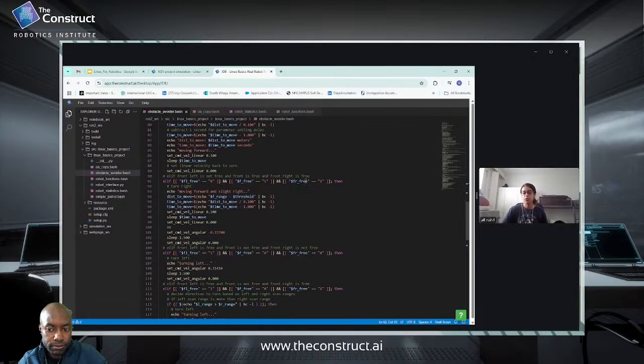So we're just doing a bunch of if statements here. So for example, here I have the front is free and the front right is free. And so this is the compound movement that I was talking about. So instead of checking the left and right sensor and being like which way can I move, I just know that since the front is already free, it's better for it to just move forward first. So I let it move forward first, and then based on this case, for example, the front right is free, so I know that the right is more free than the left without having to check the other two sensors, because I know from these values right here that there's no way that the left is going to be free enough. I set the right angular velocity over here. You see the value is slightly different. This is half of the other value, so this is like 14 degrees.